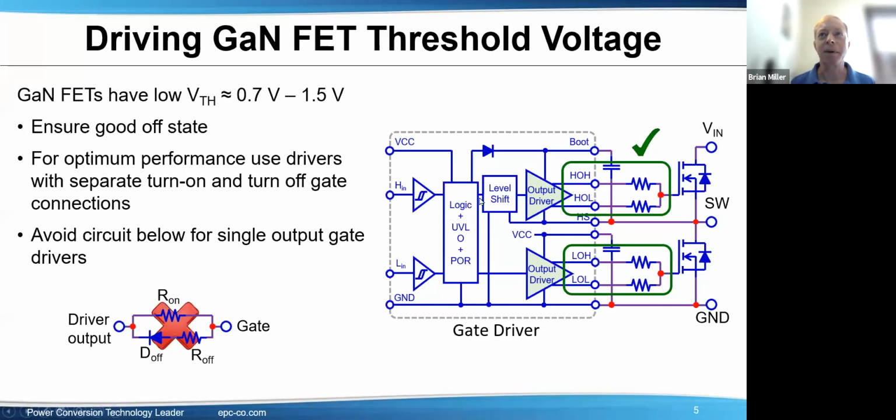By the way, on this topic, there's no need for negative voltage drive on EPC's GaN FETs. Having the output driver on the low side go down to 0 volts, that's plenty. That's good for operation.